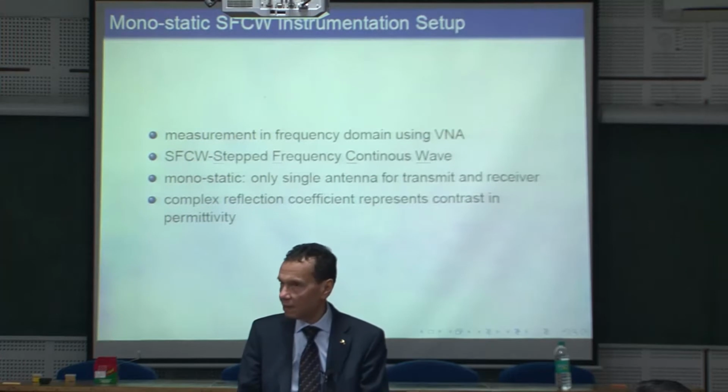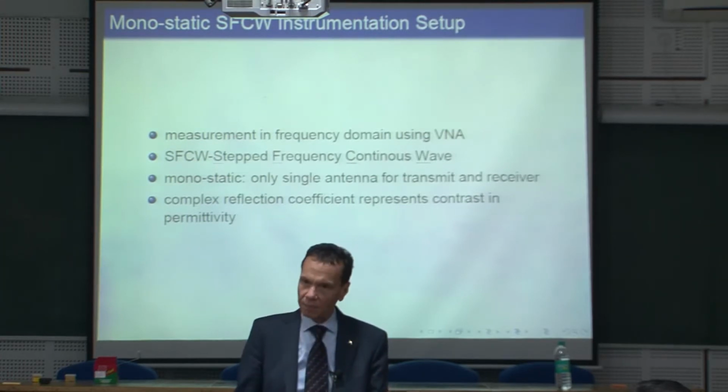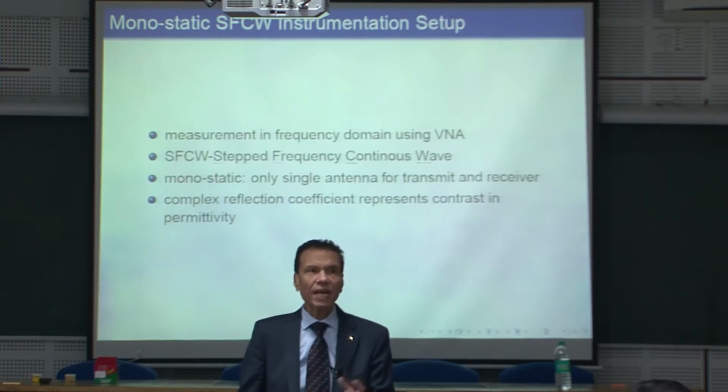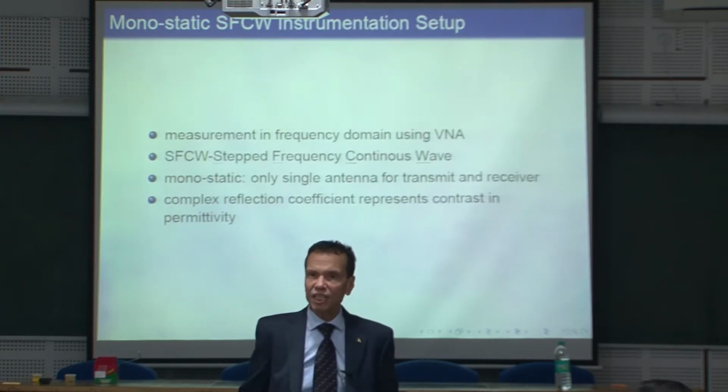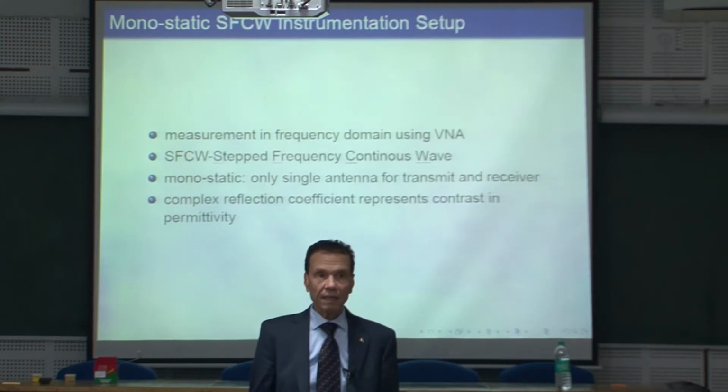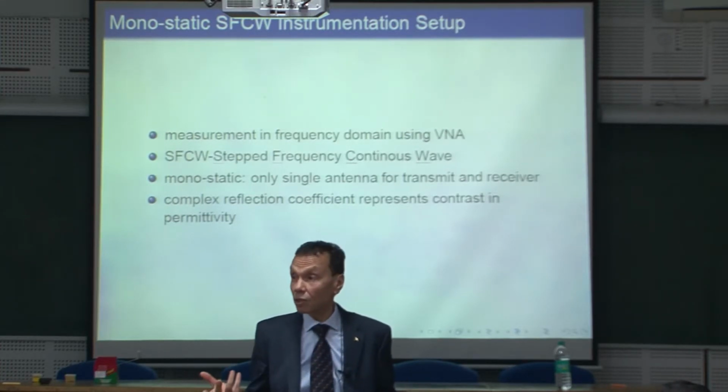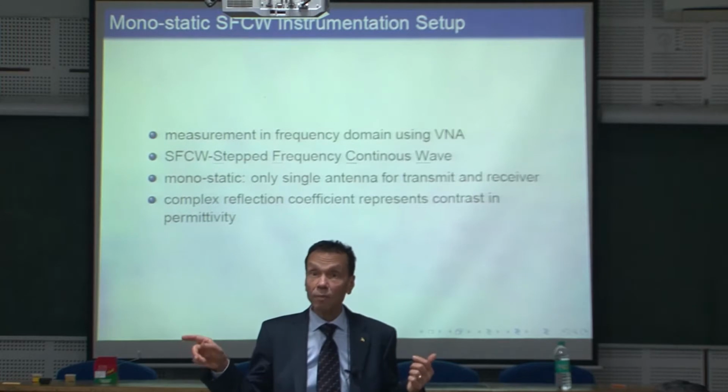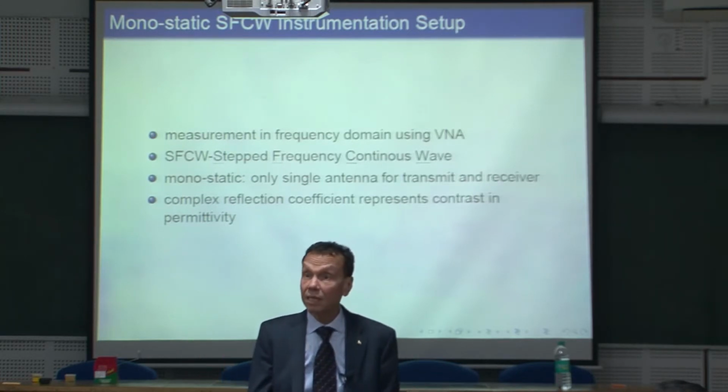Wait until the transients die out. Of course, this is fast, but I mean now from the principle. Measure the steady state and so on. So I collect my data in the frequency domain, not in the time domain. The advantage here, you can inject at each frequency enough power so that the equivalent signal to noise ratio in the time domain is really high, because the power is in your hand.